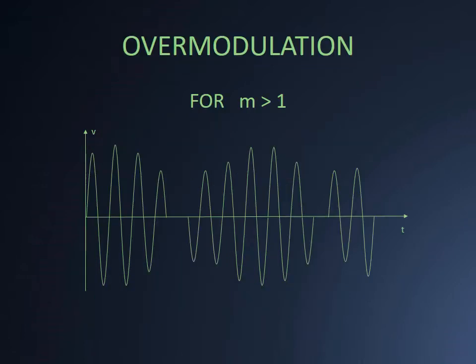If amplitude of signal is greater than amplitude of carrier wave, then modulation factor will become greater than 1 and the modulated carrier wave is said to be overmodulated, and in that case there occurs discontinuity in the wave that is not required. Thus, the signal amplitude must always be selected less than the carrier wave amplitude.